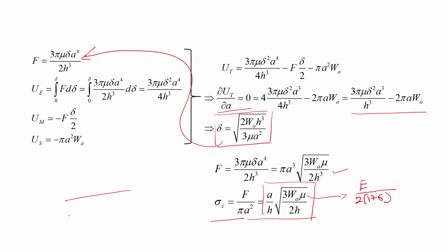the case in which this film remains bonded over here in the bottom plate, and in the top plate there is slipless contact. We can actually derive these equations, and we can also derive the expression for the pull-off load required.